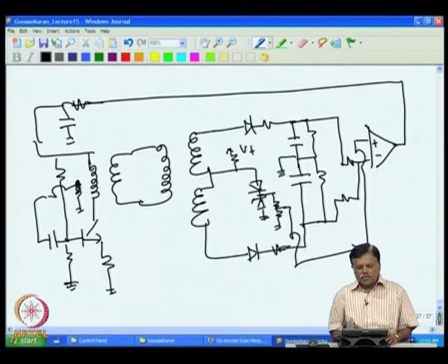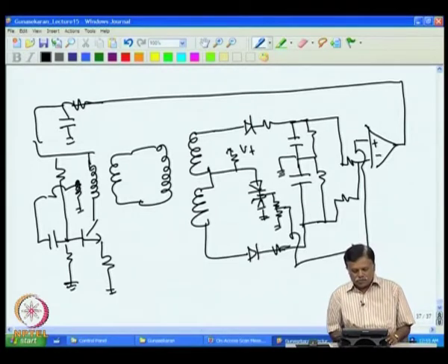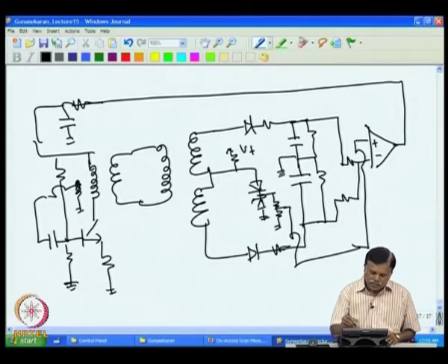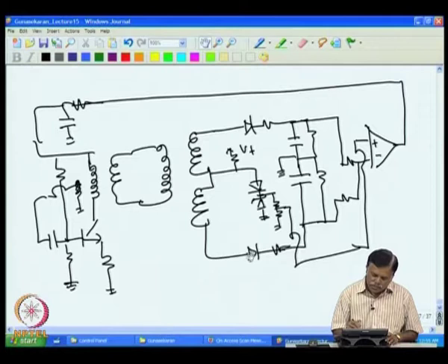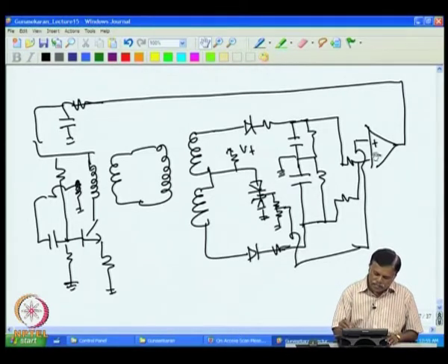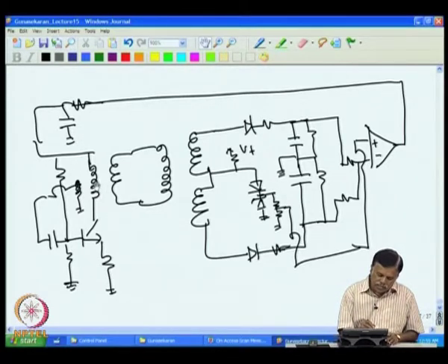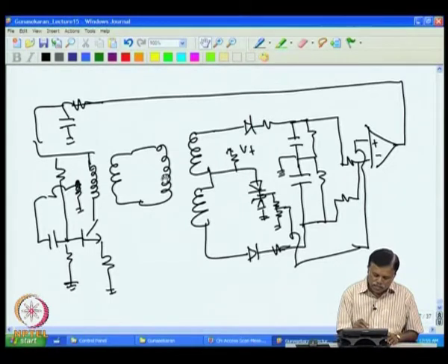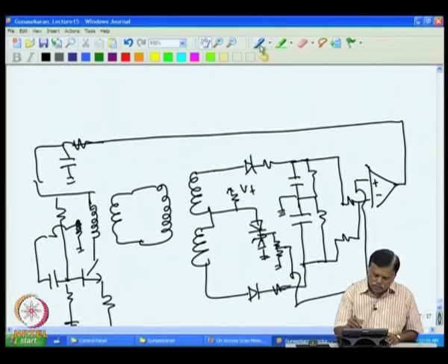So that solves both the problems, that is we have now solved the temperature problem of the rectifier diodes, and then we also solved, by giving the feedback and maintaining V1 plus V2 constant, the temperature induced error due to the resistance drift of the LVDT.